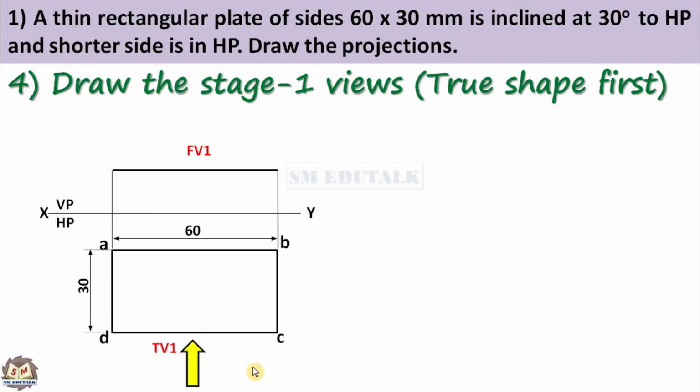They are visible points, but the points which are straight behind these points, that is A and B, are invisible. Hence, the name of the line's left end should be written as D dash bracket A dash, because here D is a visible point and A is an invisible point. Similarly, the name of the line's right end should be written as C dash bracket B dash, because here C is a visible point and B is an invisible point. That's all. Stage 1 has been finished.